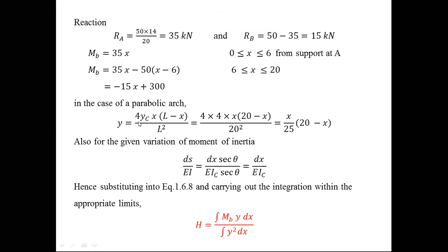And the shape of the arch is a parabola. All of you know the equation of the parabola. That will be substituted, and for simple integration purposes we can write it like this: x by 25 into (20 minus x). The remaining is the same.